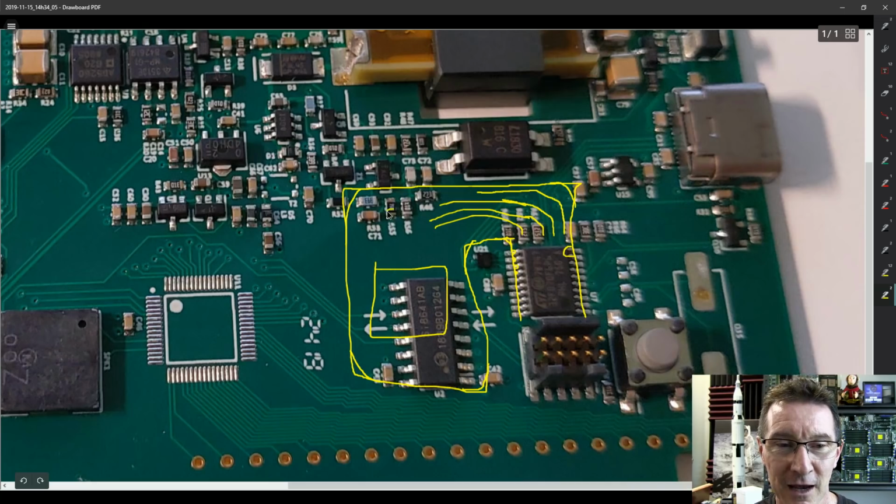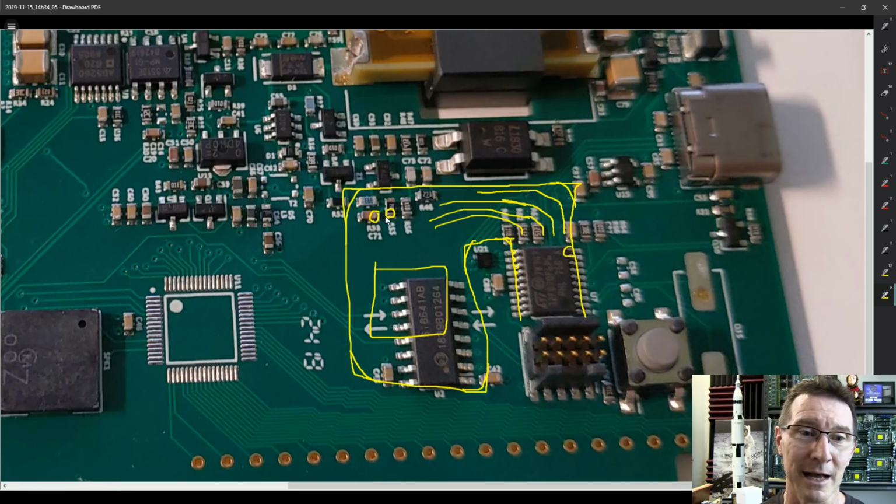Because if you had a via that just happens to be here and it was an exposed one, and then that's sitting flush on the top of this capacitor here, which is going to be larger than the physical height of the resistors there, oops, you can come a gutser and it's a short, and it might be intermittent, and that'd really ruin your day. Murphy would ensure that it'd be intermittent at the worst possible, most inconvenient time.